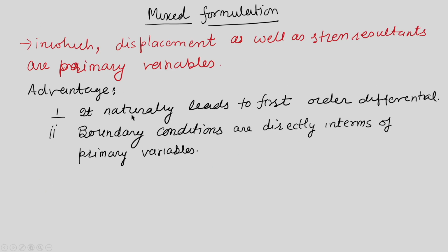Now, there is another technique, the mixed formulation. I think it was already discussed in the previous lecture. Again I am just going to review that mixed formulation technique, in which we take displacements as well as stresses as our primary variables, basically stress resultants. What is the advantage of choosing mixed formulation over a pure displacement based formulation? The very first advantage is that it naturally leads to a first order differential equation.